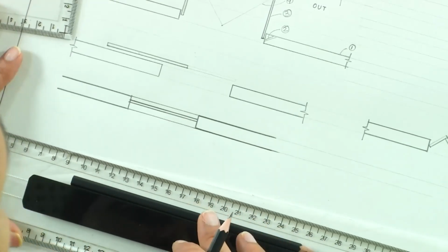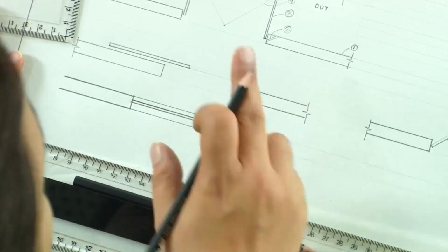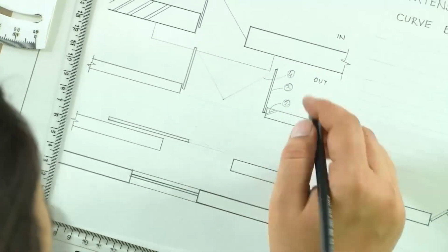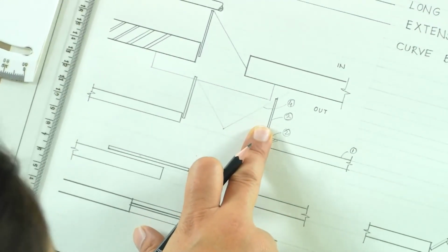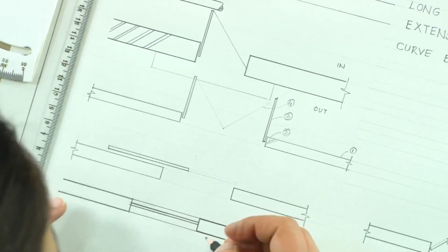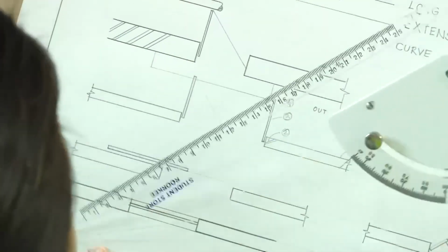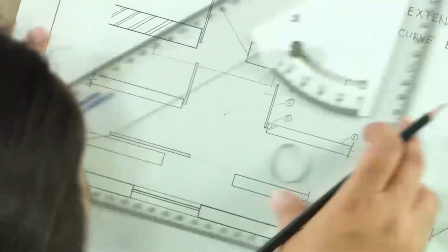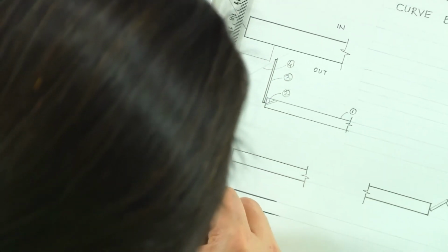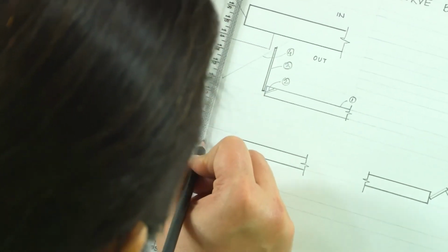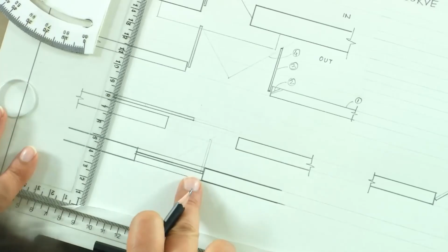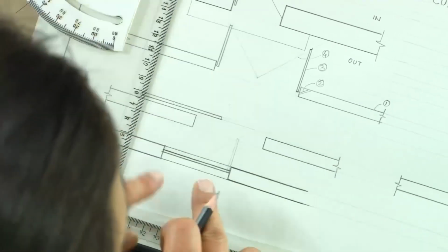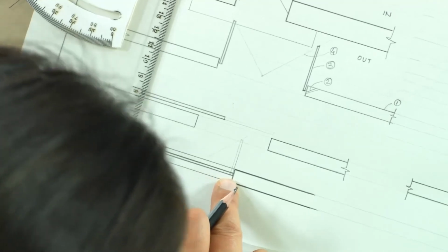Now if you have openable window, you will draw doors or the panels like the one which we have seen in door. So we will have a representation for openable window. So thin line and a window pane. So this is how we will draw the window with an openable pane. Suppose we have fixed window, we can just draw it like this.